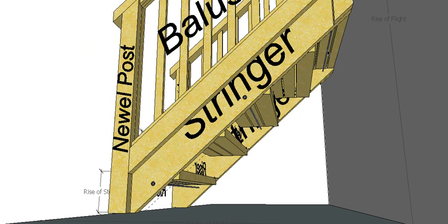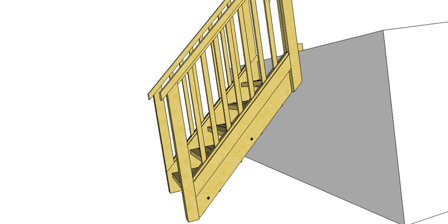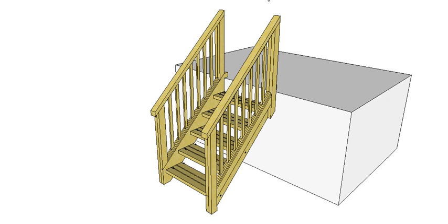And underneath, we're required with external stairs to have some sort of galvanized threaded rod to tie our stairs together. You can still have the treads nailed in, but we need to have tie rods placed underneath our treads, roughly every 1350. One top, one under the first, somewhere at the start, under the first couple of steps, one under the top couple of steps, and every 1350 in between. So there you go, there's our external staircase and all the components and terminology that go with it.